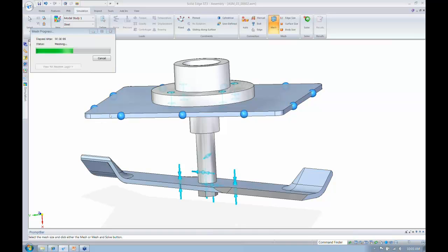I reviewed it already. So what I wanted to talk to you about here is there are 2 types of vibration, free vibration and forced vibration. Like I said, when you ping a tuning fork, that's free vibration. It's just vibrating at its natural frequency or its resonance. That's dependent on the mass and stiffness of the part, and all it means is that at that point, the amplitude of my displacement is going to be very high. So I want to avoid operating in that range.